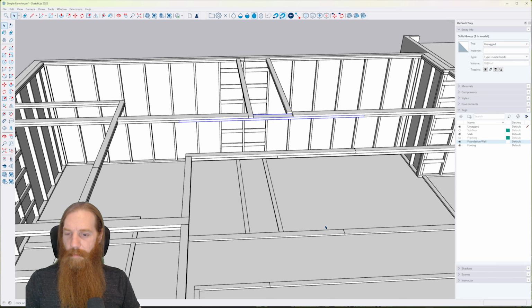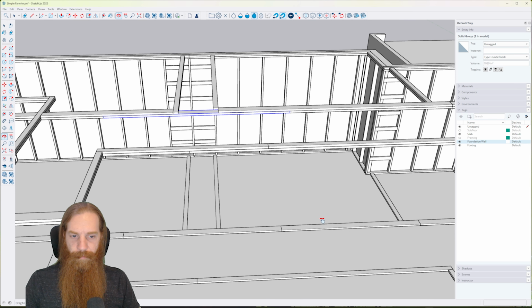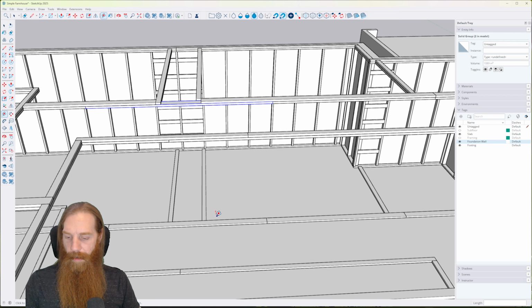That seam right there might create a little bit of a problem when I'm doing my doorway, although I think it'll be okay. Because I'm going to put the doorway basically all the way into this corner with probably only 6 inches there at the end. So 6 inches plus 36 or 38 for a door opening. Yeah, it's going to be close. Now that I think about it, I probably do want to extend that down a little bit further because of that. So 11 foot.